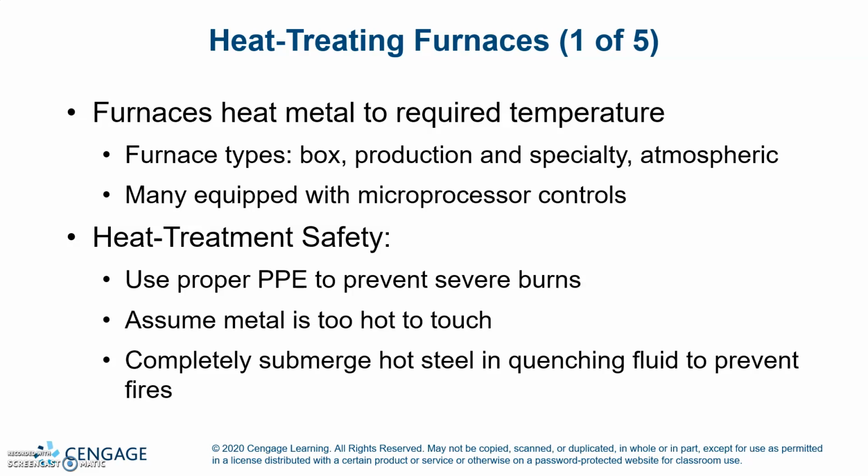Heat treatment safety. Use proper PPE to prevent severe burns. Assume metal is too hot to touch. Completely submerge hot steel in quenching fluid to prevent fires.